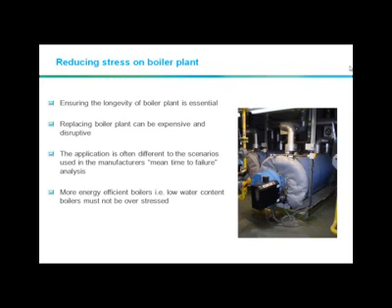And as a part of that, with increased pressures to get higher efficiencies, some of the existing boiler plant in these buildings becomes underutilized, because with more innovations and better efficiencies, this boiler plant doesn't shrink overnight. It's probably there from the original design and application it was designed for. So sometimes this boiler plant can be underutilized, or overcapacity as it is often referred to. And also with the advent of more efficient boilers, i.e. low water content, it's really important that boilers are not overstressed.